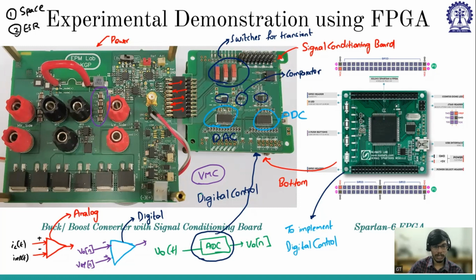So it is up to the designer's choice how they can consider 100 microfarad 4, or they can take 10 microfarad 10, then it becomes 100 microfarad, and 300 microfarad, then they can take 47 microfarad or 22 microfarad. So you have a wide range of capacitance values that are available. So it is up to your choice how many capacitors you want to put and what value of capacitance you want to select.